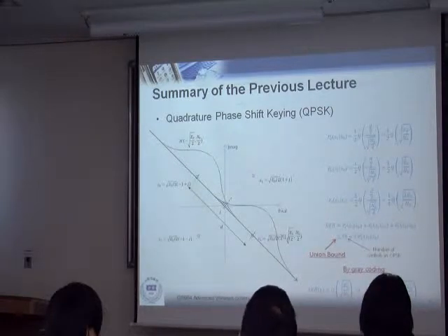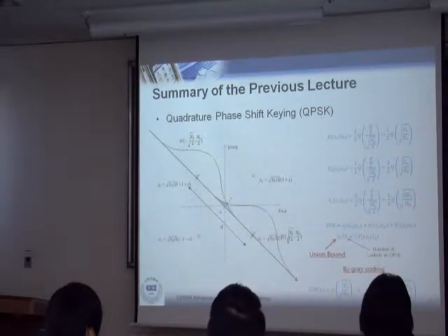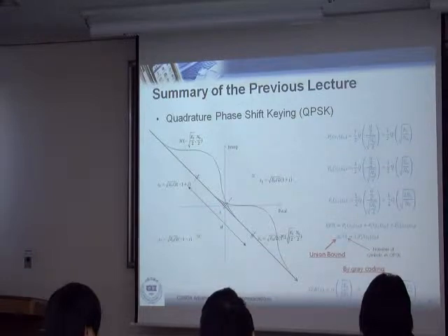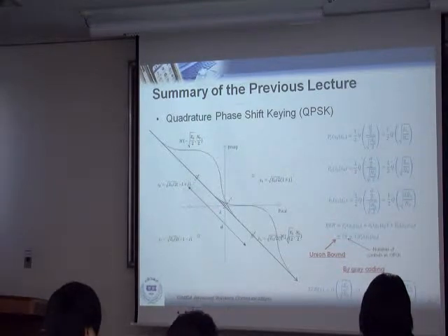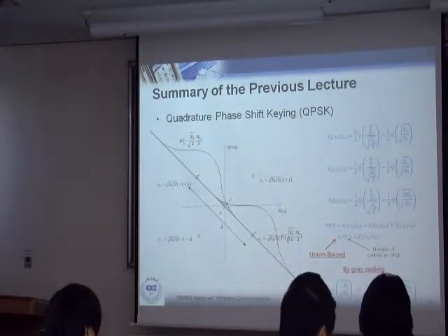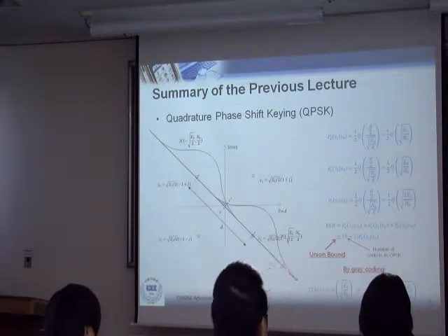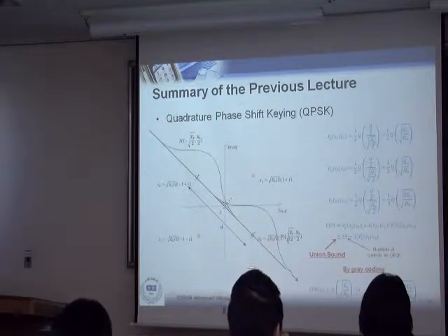What is the bit energy for a QPSK signal? In case of QPSK, the bit energy is going to be half, right? Because this is one symbol, and the energy in this symbol is 1. But inside this symbol, we have 2 bits, right? So Eb, the bit energy, is just the energy in 1 bit. So it's going to be half, because we have 2 bits, right?